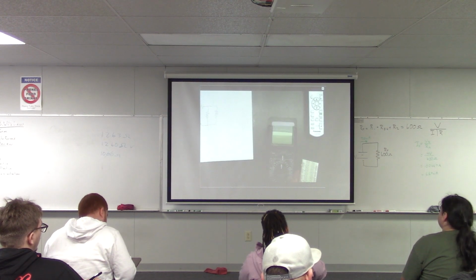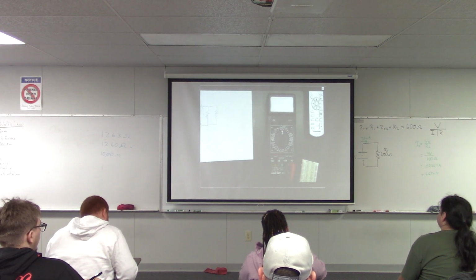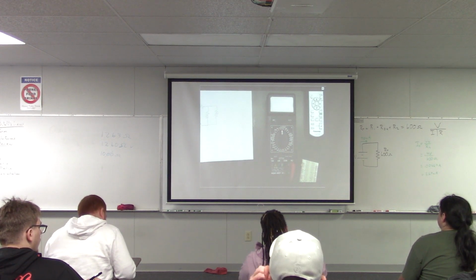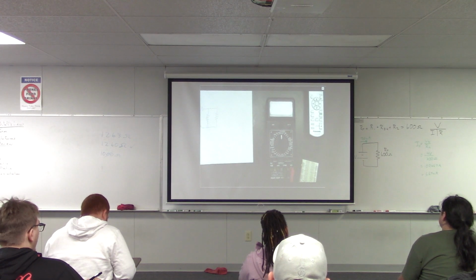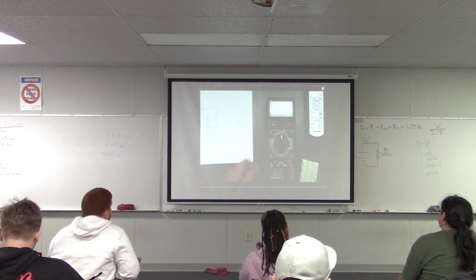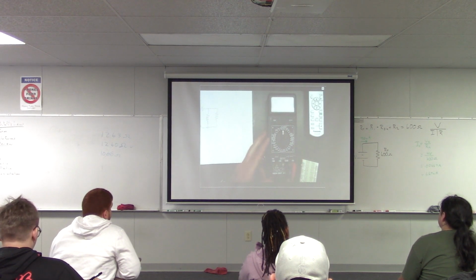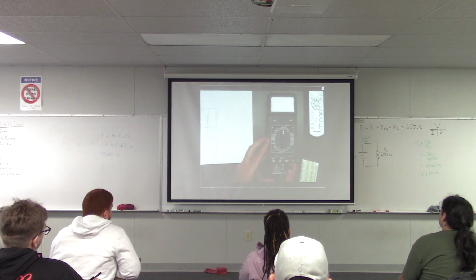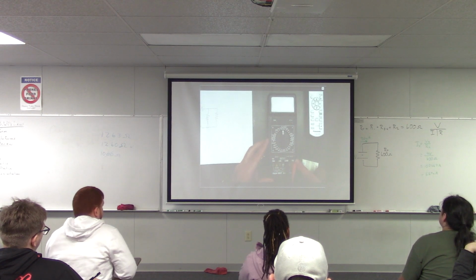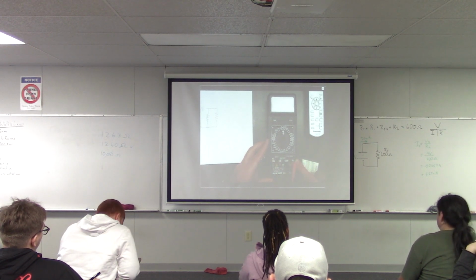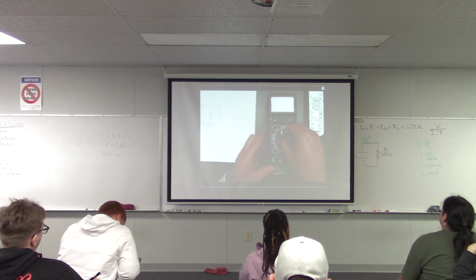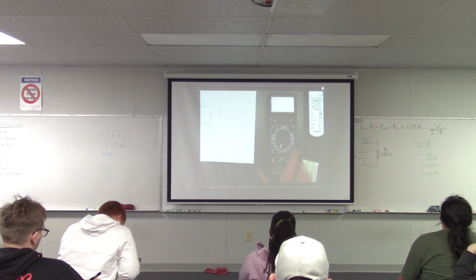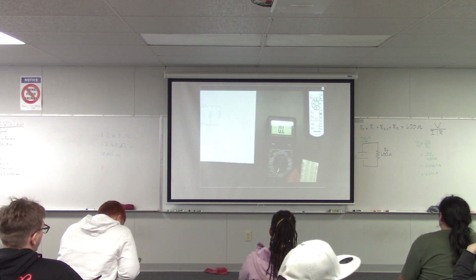So the first thing I would recommend is that you actually measure your resistor values using the meter. Remember, the way to do that is you put the black lead in the common port, like always. You put the red lead over here in the rightmost port where it indicates resistance. Then you put the dial into resistance measuring mode, which is one of these positions over on the left-hand side.